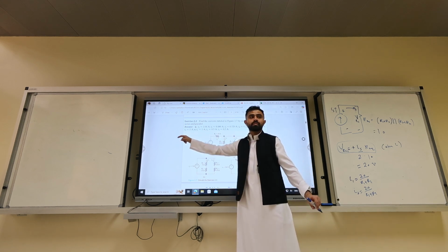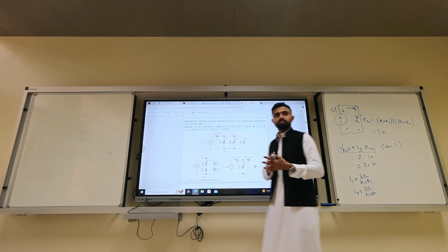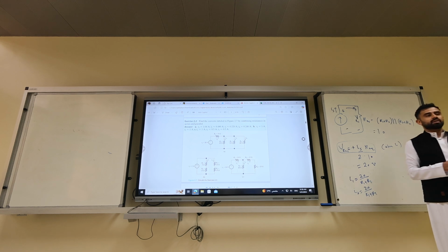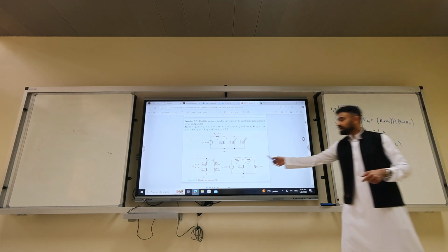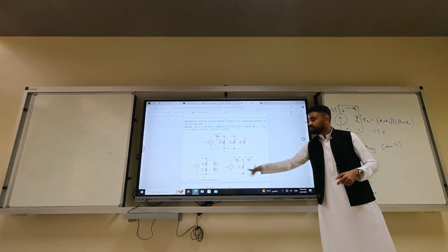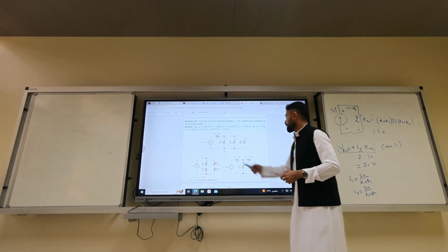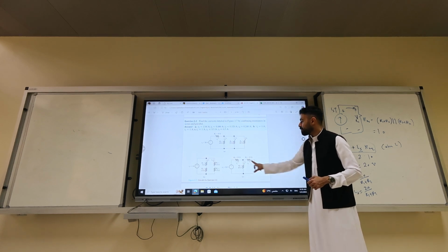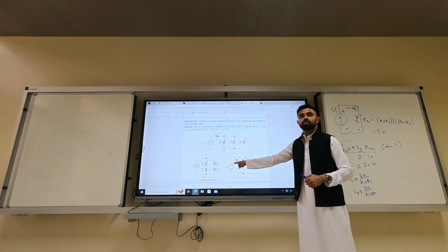Get it? When you just say because they are parallel and they are equal, you can say that, but that's not always the case in the exam. I'm not doing KVL in this problem. Now, problem C is another problem. Problem C, what he is asking for is to calculate I1 and I2 and I3. To calculate I1, you get 15 plus 25 in parallel with 40 in series with R1 and divide 30 over R equivalent, you will get I1.